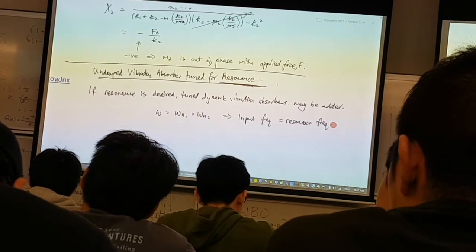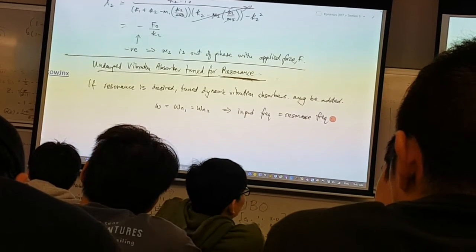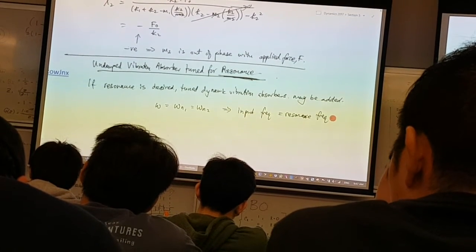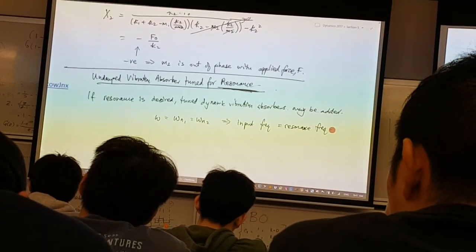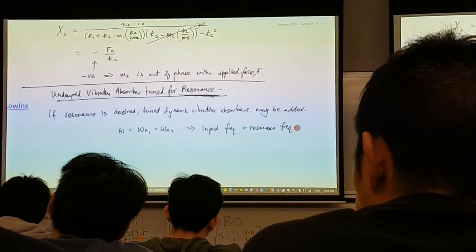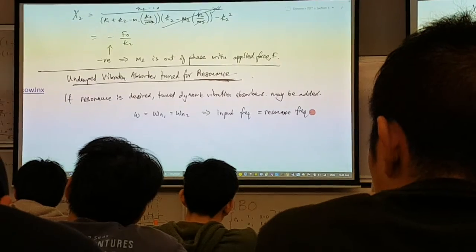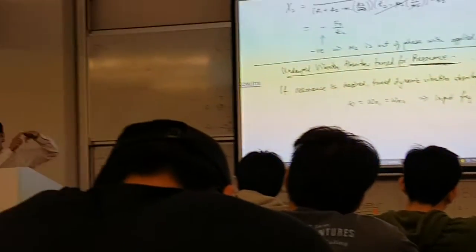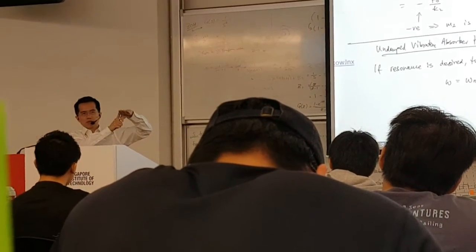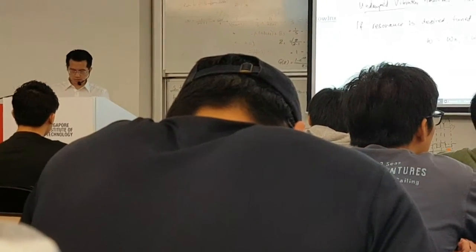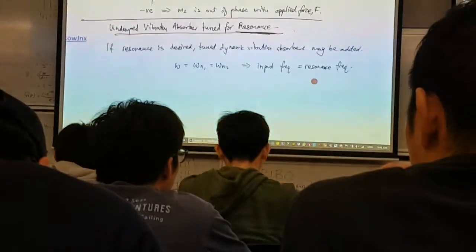I have this piezoelectric material, which is a material that, upon stress, will produce electricity. I would want to resonate this because I applied 2 layers at the top and the bottom of the cantilever. If I can make sure that this resonates, then I can harvest a lot of energy. So that's why there's also a design for the system to resonate.